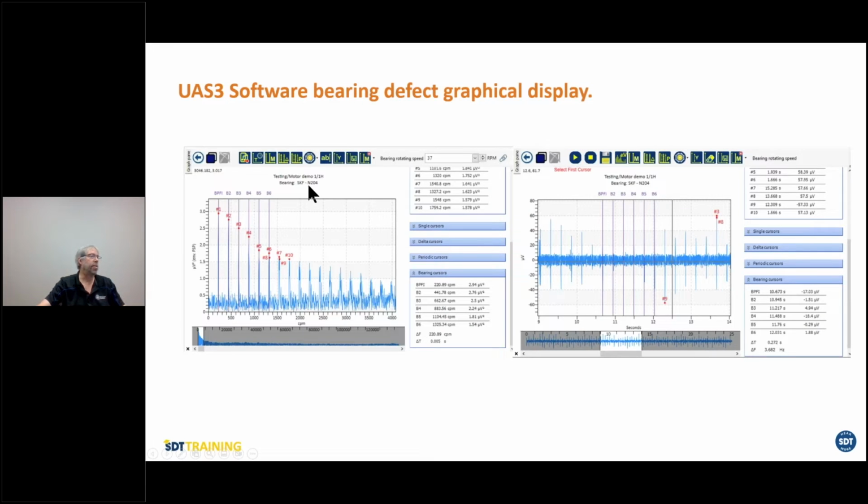That gives us, when we look at spectra, it overlays the bearing defect frequency on top of your spectra. If they match, guess what? This one has an inner race defect. Look how slow this thing's going. That's very important here: 37 RPM. I can detect problems at 37 RPM with ultrasound. Over here, the impacting is perfectly proportional also in the time waveform. So I have certainty that my SKF bearing has a problem which was detected with ultrasound.